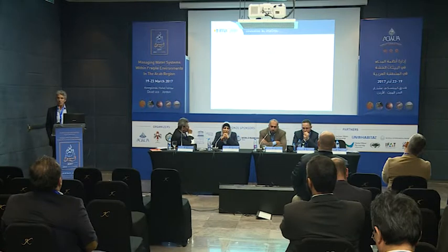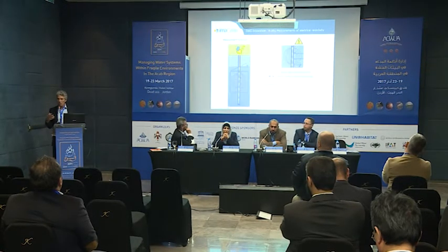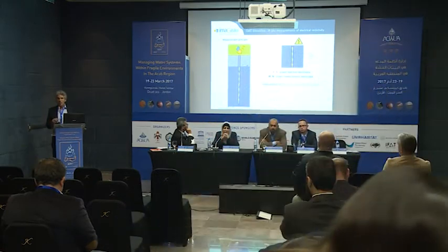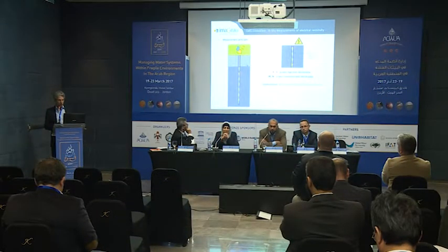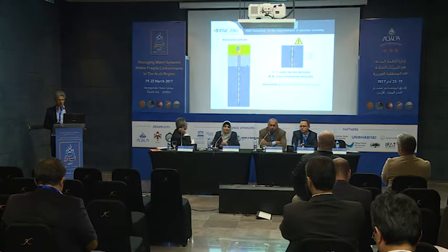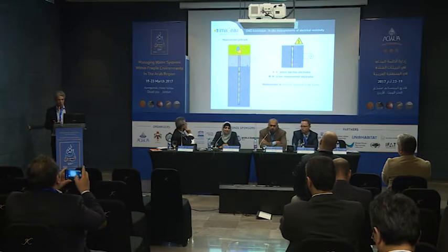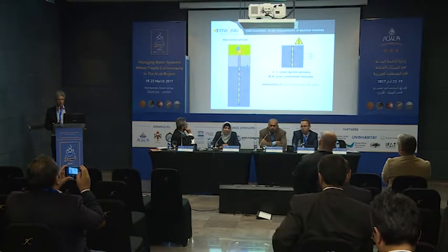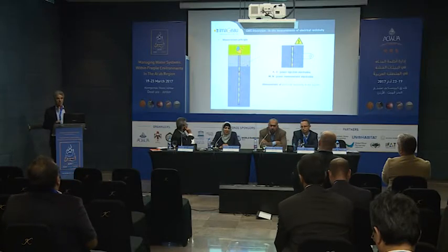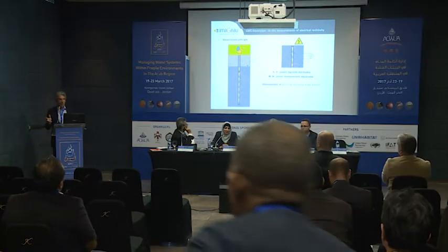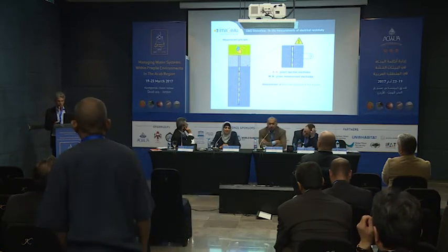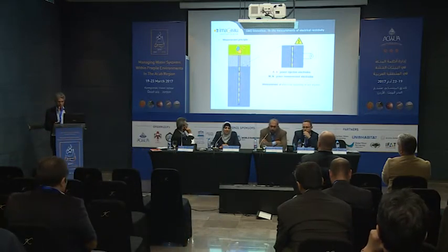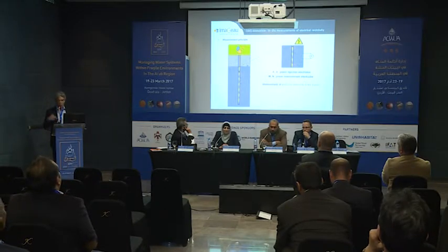Now let's talk about innovation. The GMD is a monitoring device that we have invented at ImaGeau to know exactly what happens in the underground water resource. The innovation consists in situ, automatic, and repeated measurement of electrical resistivity. As you can see here, we inject power into 2 electrodes, and then we get the power back, and we measure it. So we have the measurement of electrical resistivity in the whole aquifer.